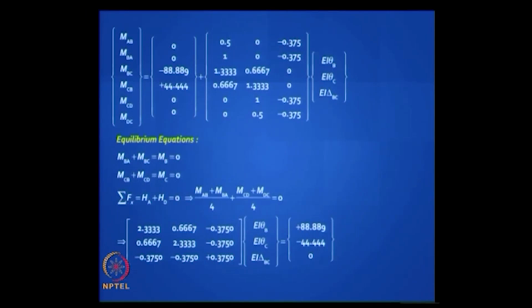beautiful part about this is the vector that you get here is caused by the loads. The left side is completely a property of the structure. You change the loads, only this will change, this will not change. And so we will see how you can generate that stiffness matrix from first principles. I am stepping ahead into matrix methods, but I want us to go through that exercise. We got this blindly by just applying equilibrium equations, right, but with our eyes open can we generate this matrix? Let us do that, because then you have a real understanding of the physics behind the mathematics, okay.